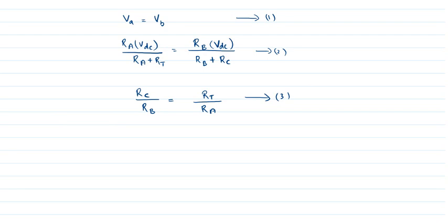The reference condition is a specific value of the physical quantity at which the bridge is balanced. So the bridge is balanced initially at a desired reference condition. However, as the physical quantity to be measured changes, the resistance of the transducer also changes, which causes the bridge to unbalance. So the bridge is balanced only for the reference condition.